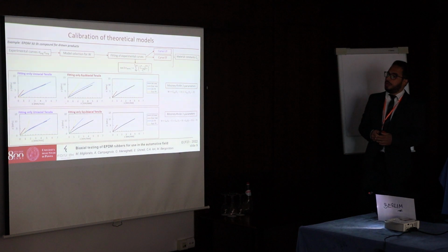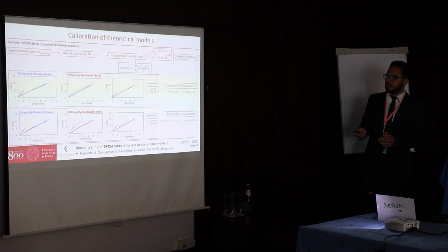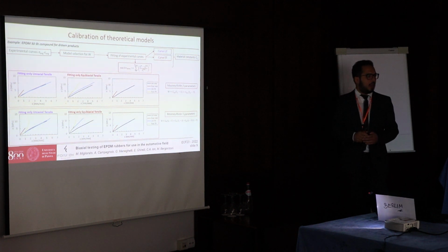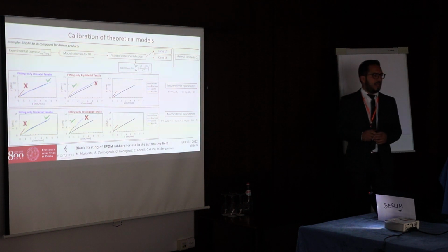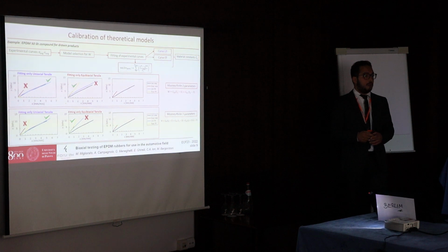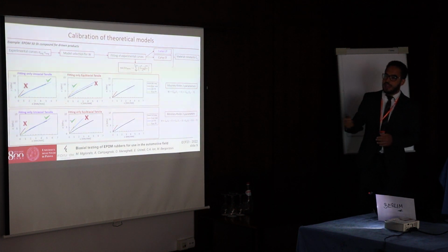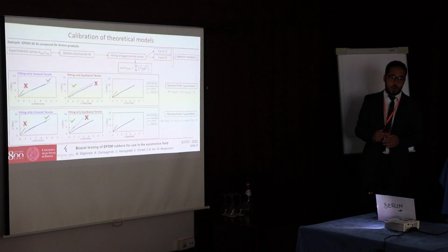And it should be noted that, in principle, if the fitting between the model and the experimental results is performed only on a single curve, either uniaxial or equibiaxial, the model allows to predict very well the stress state on which it is calibrated, while it can significantly deviate for stress states different from the calibrated ones.